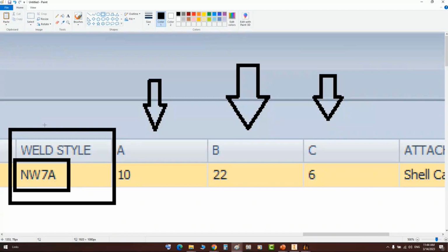After that, we will add the dimensions for the tank, add the balloons, and reflect the balloon number in the drawing so it matches the same item number in the bill of material, inshallah.